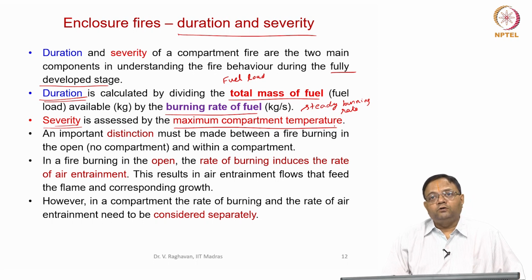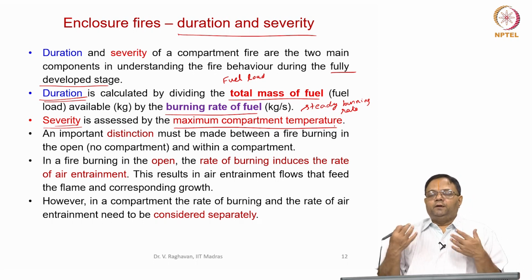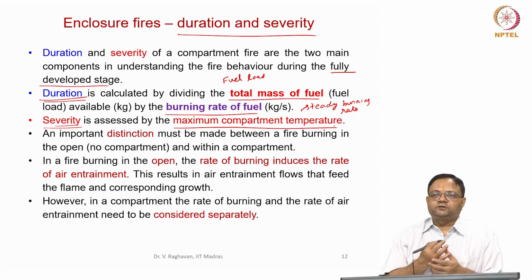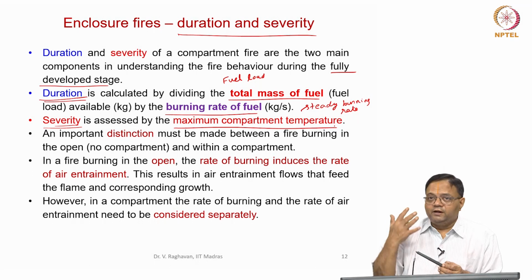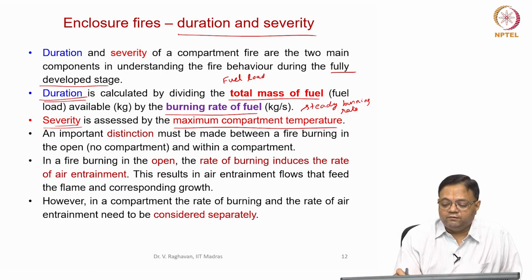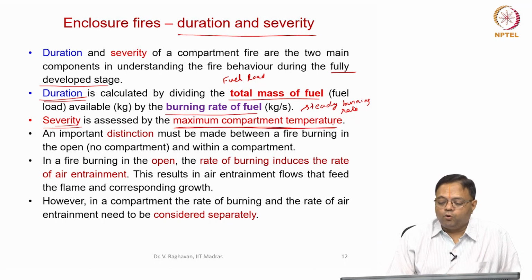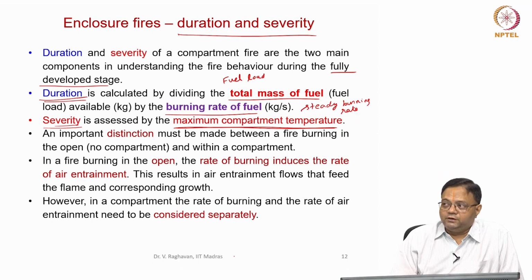which is going to cause structural failure, because when the temperature is higher, the structure will be heated up, but the structure will not lose the heat as soon as the fire decays. So, that is the reason we need to worry about the maximum compartment temperature.